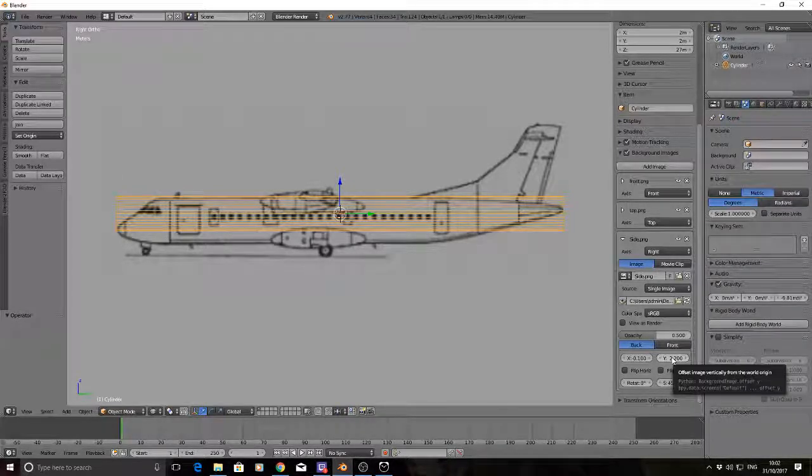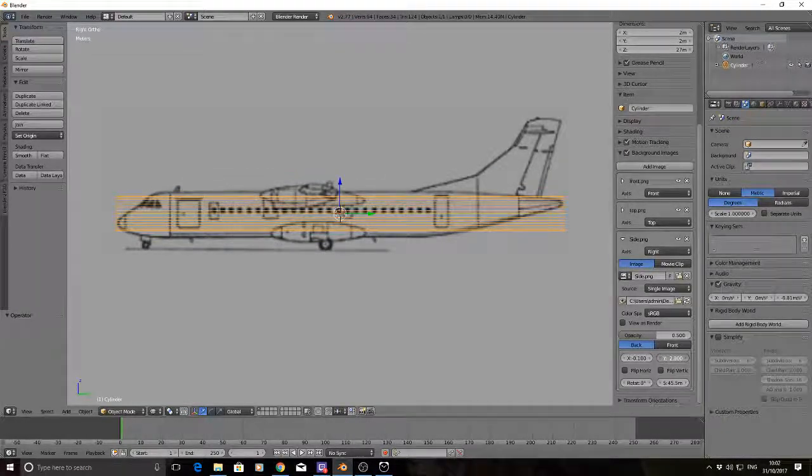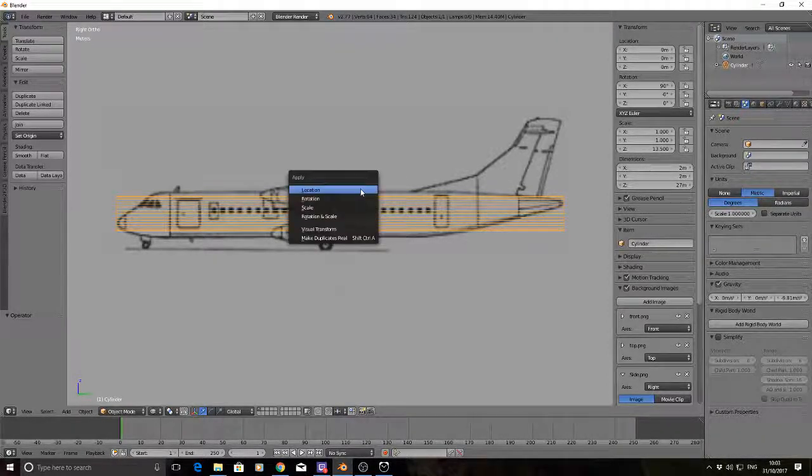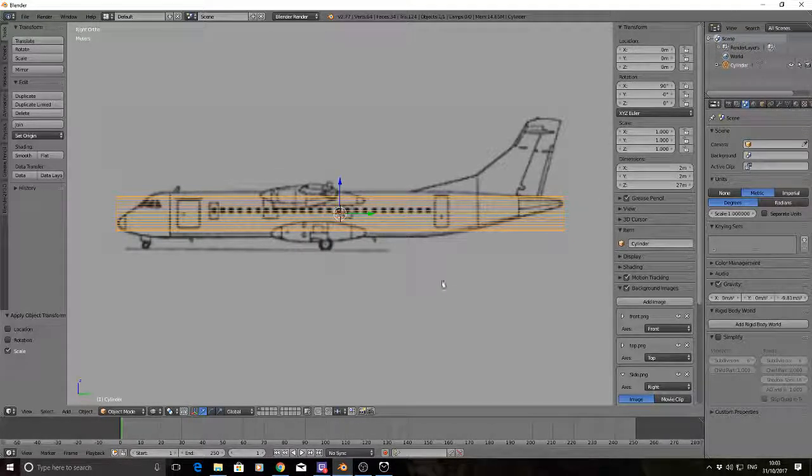First things first, we want to just move the fuselage roughly to the center of the image, and then we're going to start manipulating the shape of the object. Okay, one thing to note, scale, which is here, has to be 1. If it's not, the object becomes flat, or it doesn't even show up in Sim. To do that, Control A, scale, and then it changes it to 1. So that's how you do that.